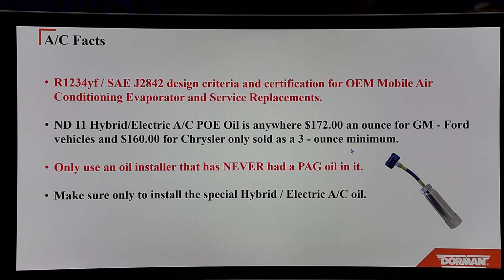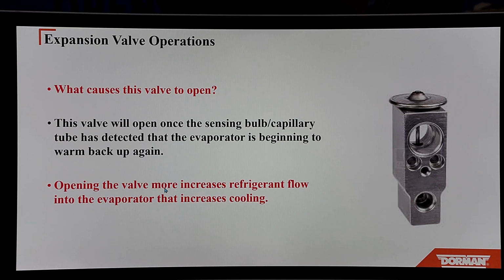Only use an injector that has never had PAG oil in it. So see this? We have these. They get cleaned out, and the only oil you put in is the recommended oil. Do not put anything else in the system. If you're just going to add a couple of ounces with dye, you can use a POE oil, but for the compressor, you need to use the special compressor oils. Make sure to only install hybrid/electric AC oil.